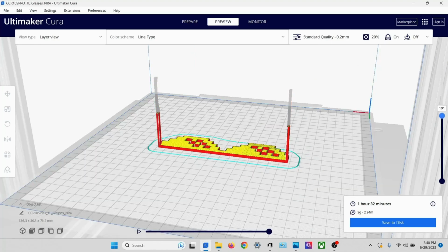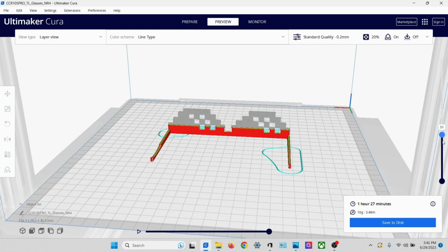This orientation is decent and would not require supports, but will spend as much time traveling as printing and could potentially produce a lot of stringing while printing. This would be the ideal orientation for printing this object, although the object would require supports for the empty space, but it would waste very little time traveling.